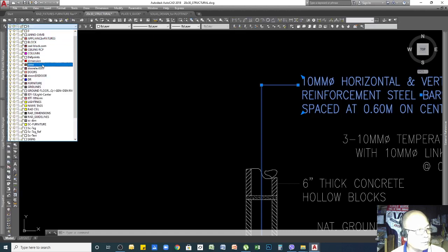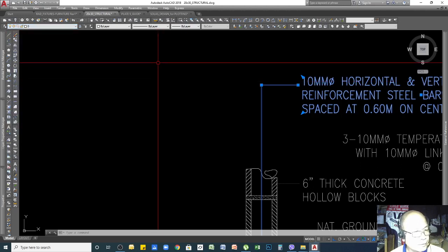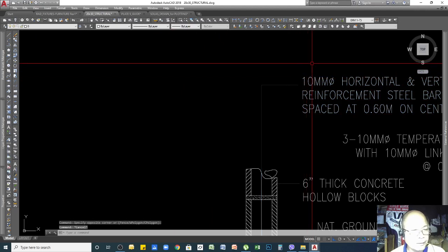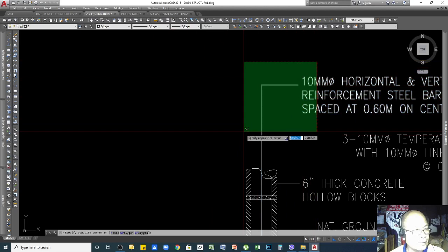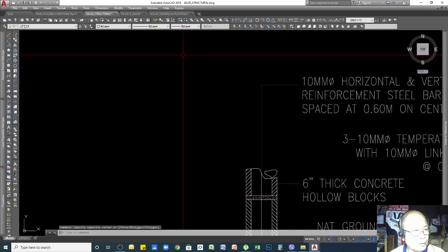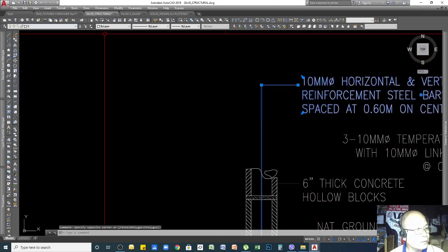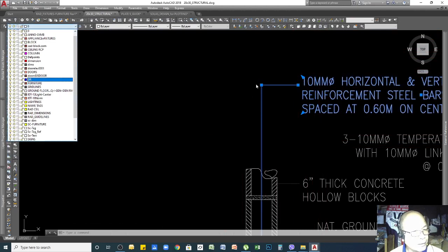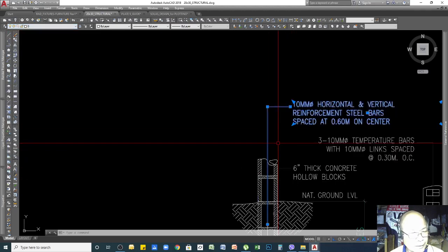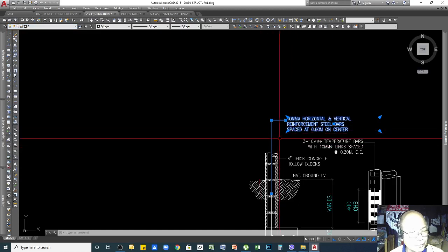This is the one I mentioned before: if you just copy any drawings from other files, all the information of it will go inside your file as well. That's why I don't want you to import external files or drawings directly into your drawing. Instead, you have to open that file first and then change the layer into zero. If it is already set to zero, which I'm going to do when I send it to you, then when you copy it and import it to your drawing, it is under the zero layer.